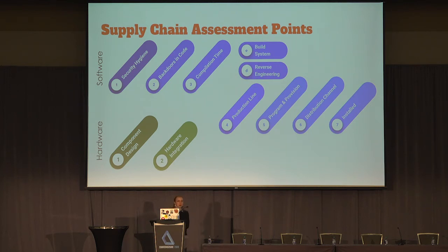So you develop a specification. Usually that's done in-house. For SuperMicro, that was done in California. And that can be easily checked. So you have one specification, one RTL file for the silicon, formally verify or just code review. This can be easily checked for backdoors or other failings in-house. Now this is the easiest time to insert a low-level hardware backdoor if you do control this process, right? If you controlled everything, the manufacturing, you could say, okay, we'll just insert a backdoor here. It's cheap, it's easy, everyone's happy.